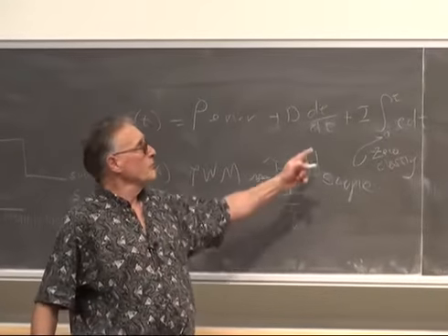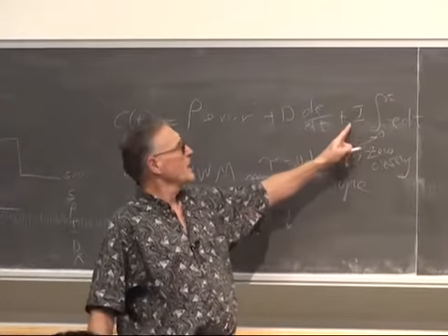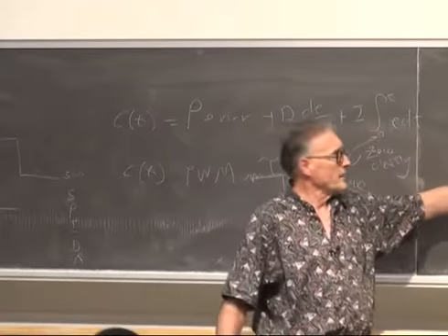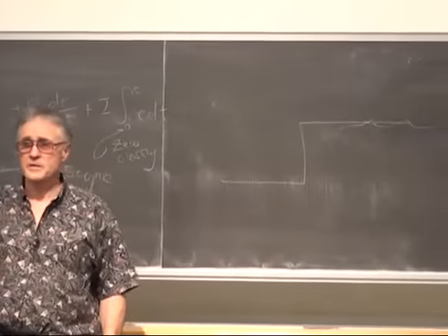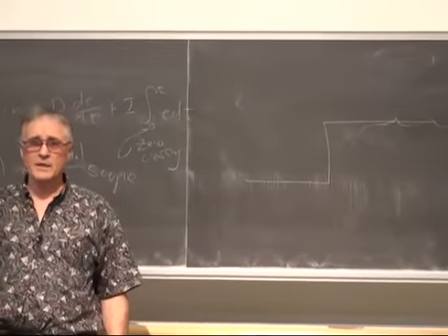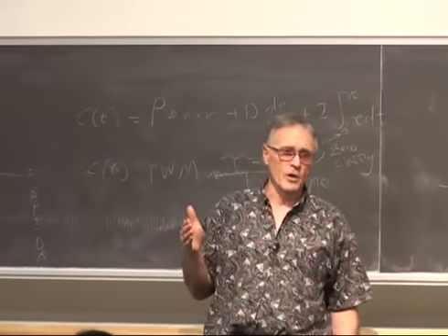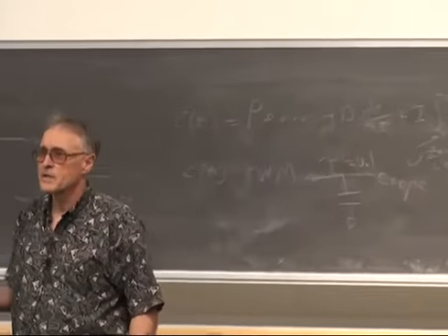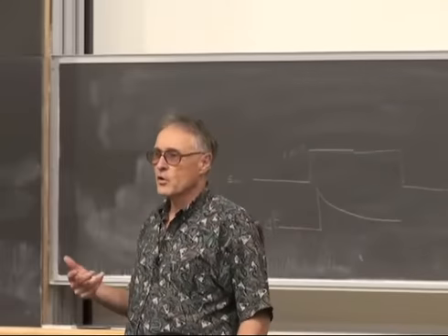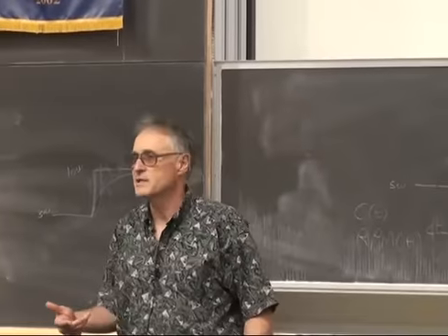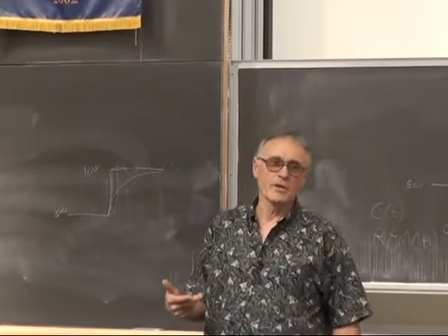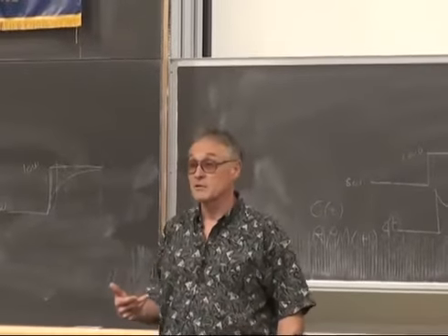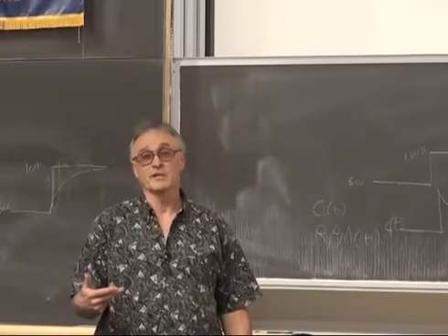So if you program this up with a fairly small integral term and reset it to 0, you're going to hear the system go eek eek eek eek. You'll hear the torque, and since the PWM is running at a kilohertz, the torque pulses will be at a kilohertz, which are easily audible. So even though the motor isn't vibrating very much, you're really sensitive to a kilohertz. So you can hear the thing. You can actually tune it by ear.